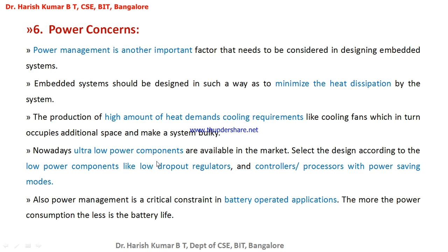One fortunate thing is, nowadays we have ultra low power components. When you're designing the embedded system, you should go for using low power components. When you're using low power components, obviously the heat dissipation will be reduced, and you don't have to use cooling fans for cooling the temperature of the components.